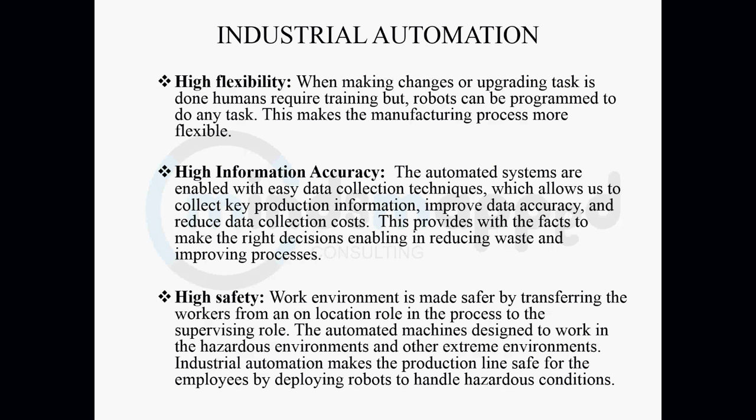Like with the data we get, let us take the example that you just got from the hot water with the coming of the cooling water and the two sensors. The sensor can give us some feedback, and based on that, we can decide to increase or decrease the steam rate.